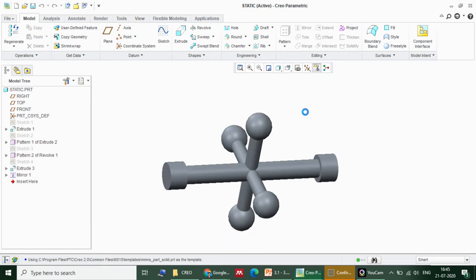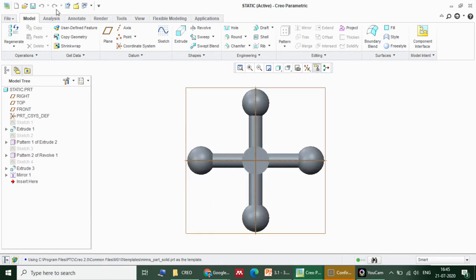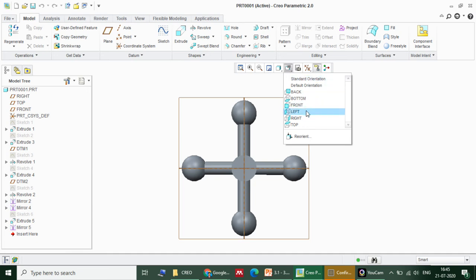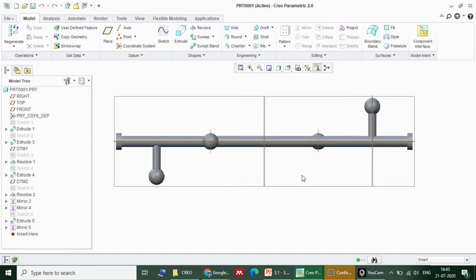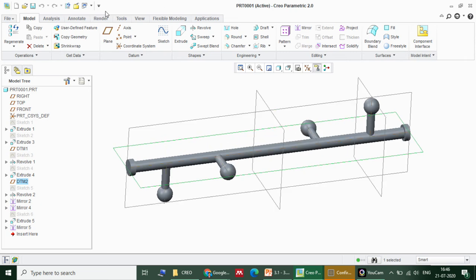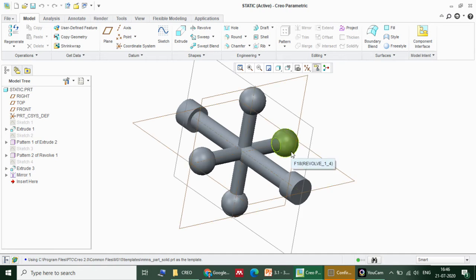Now I am going to put it in the side view. Can you differentiate this and this? No difference. Correct? But when you take a left view, you can see the masses are far away. This is in one plane, this is in another plane. There is a small distance between these two, and a further distance between these two, and further between these two. So this system requires dynamic balancing, whereas this requires static balancing. Clear? That is the main difference I wanted to convey.